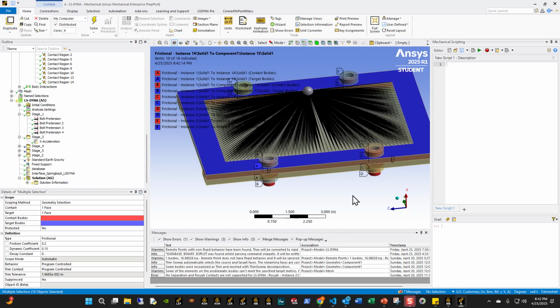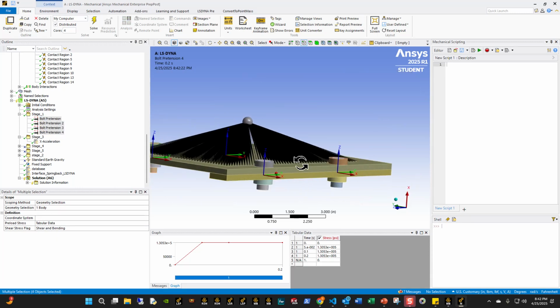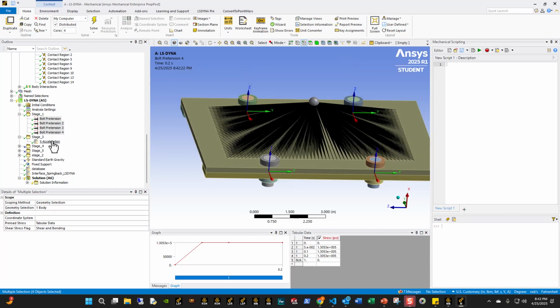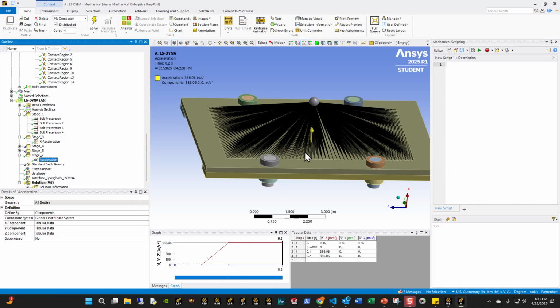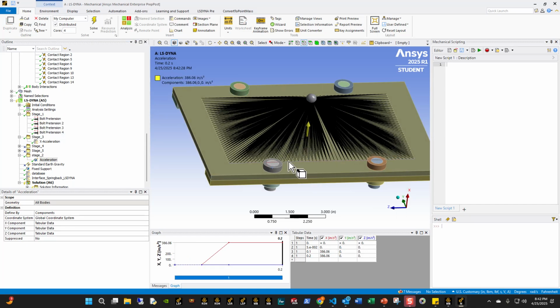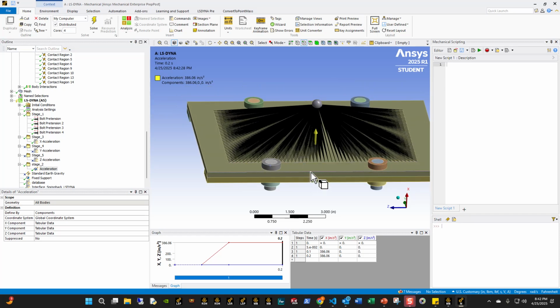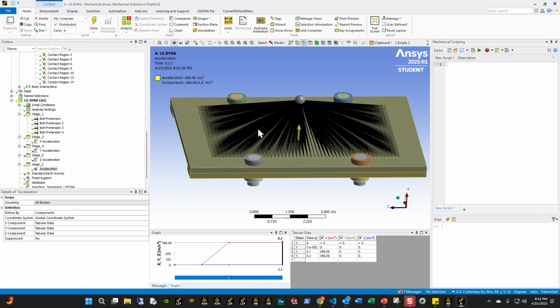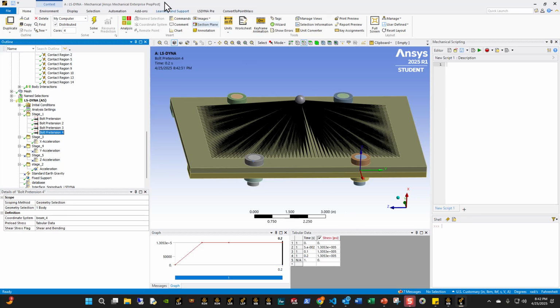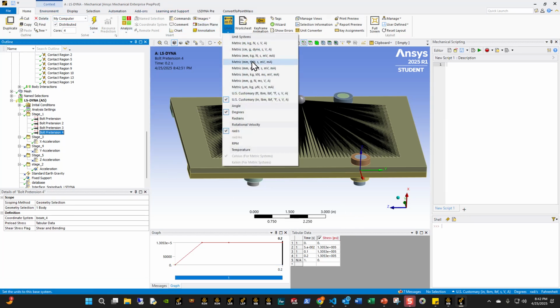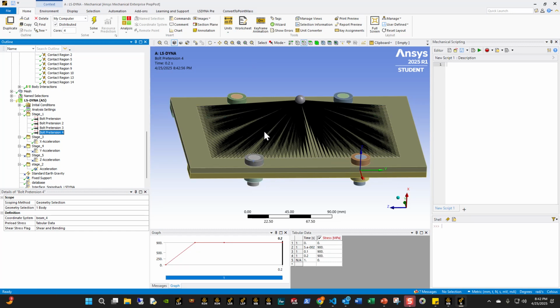So what I wanted to do here is apply a bolt preload, which is going to tighten the plates together. I'm then going to apply gravity, which is going to put this under the static condition of having gravity acting on it. And then from that point forward, I'm going to apply an acceleration that's greater than gravity in the x, y, and z directions. Based on the arbitrary bolt preload that I've applied to the 4 bolts, I wanted to see whether it's going to hold up against the arbitrary acceleration load that I generated.